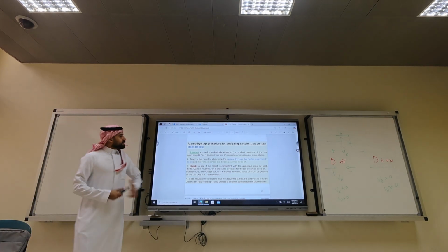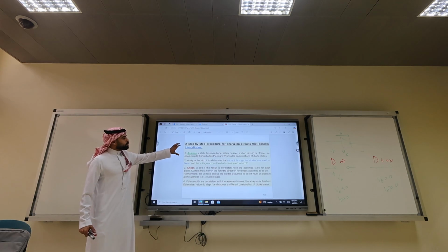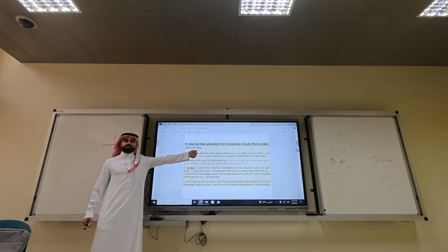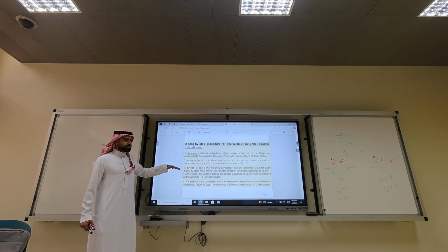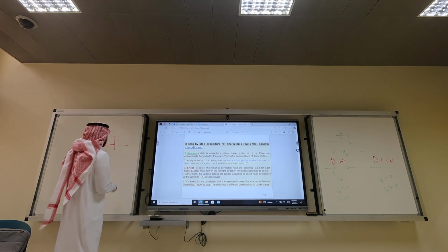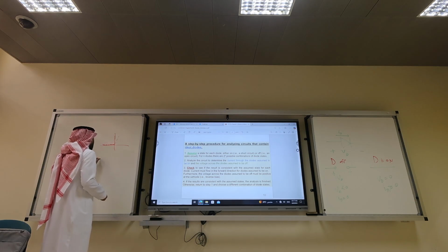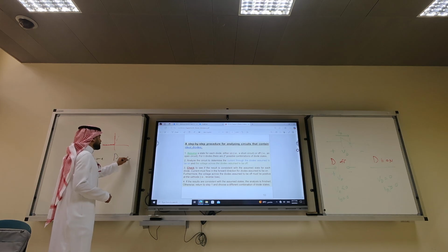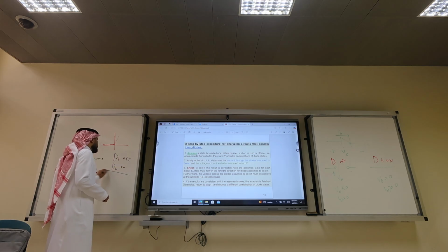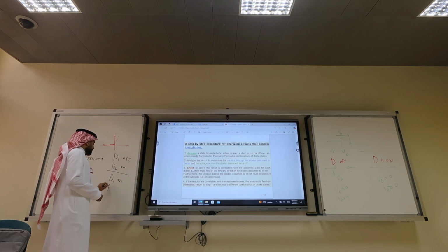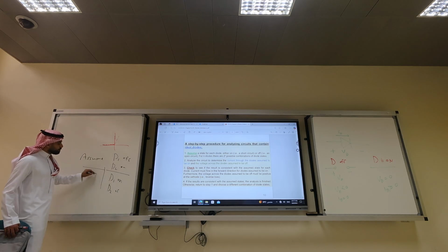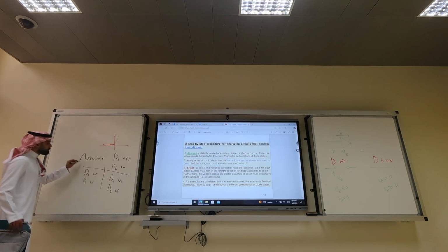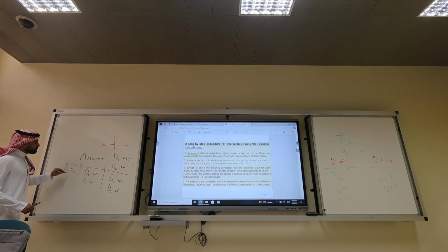Okay? So first, what's the keyword here? Ideal diode, okay? How many steps do we have? Assume, analyze, and check. You have to assume. So in your circuit, you have to say the word assume. Maybe we say diode 1 is off, diode 2 is on. Maybe diode 1 is on, diode 2 is off. Maybe diode 1 is off, diode 2 is off. Maybe diode 1 is on, diode 2 is on.